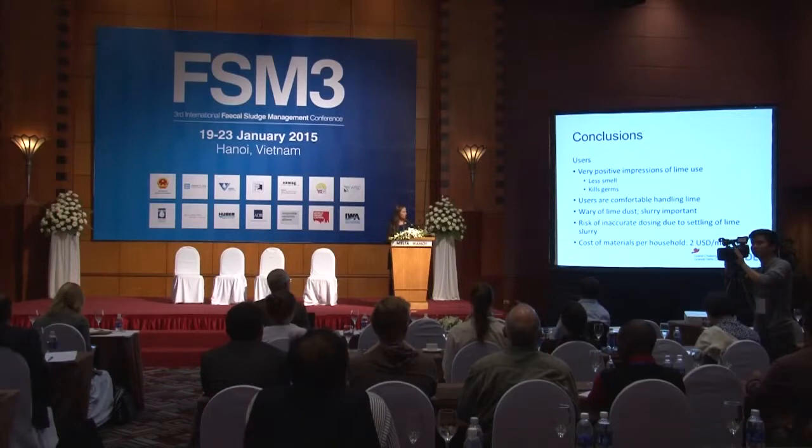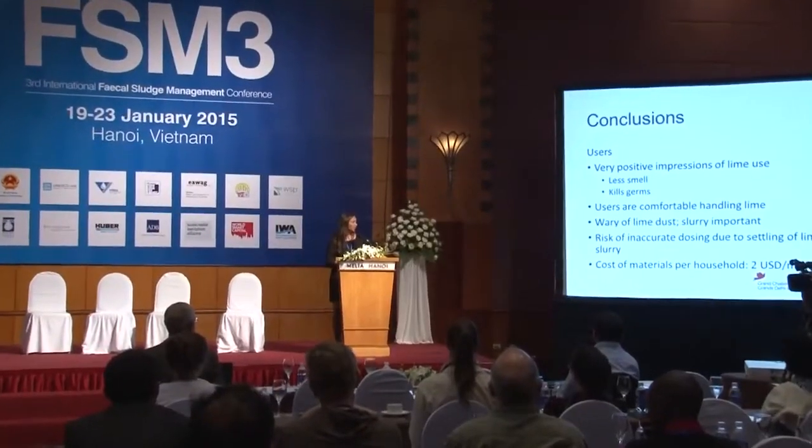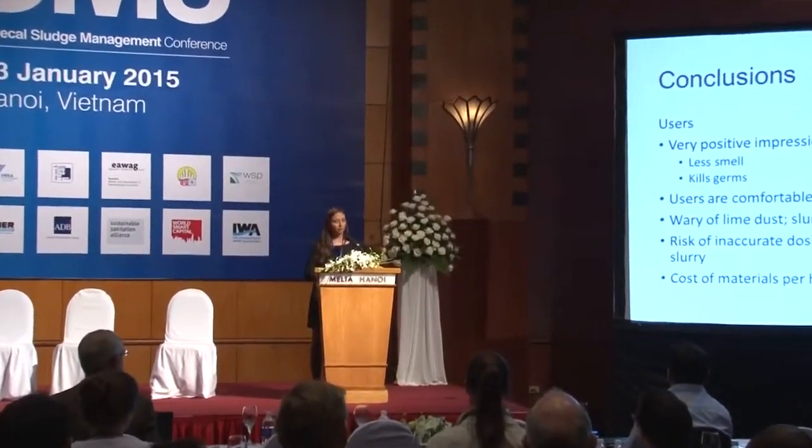There is a risk of inaccurate dosing due to the settling of the lime. Lime isn't very soluble, and we asked the users to mix and resuspend the lime before applying it, but this wasn't always done correctly. The cost of materials when using lime, where the user was applying it, was about $2 per month, so it could potentially be a feasible approach.